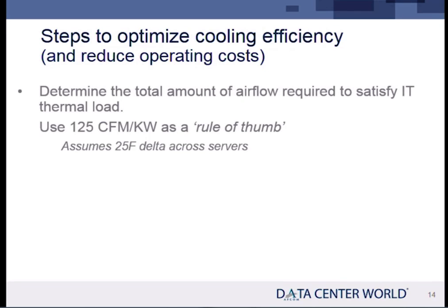Can we conclude that this is an existing data center replacing a normal analog fan with an EC fan unit? Yes. Power consumption by that particular cooling unit will reduce by 50%? You can't assume it, no. The question he's asking is, if I move to EC fan and variable speed fan, can I assume energy savings? No, because you haven't yet dealt with the issue of air management.